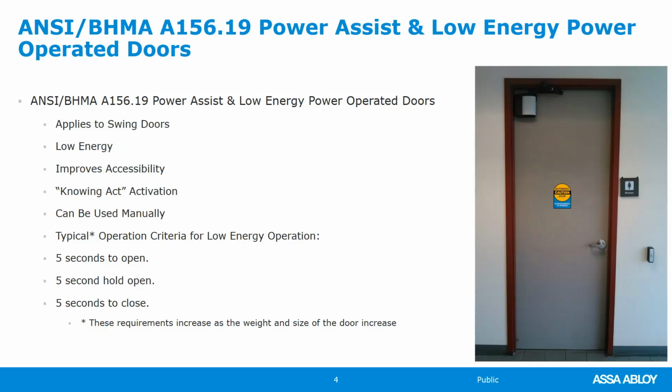Must take at least 5 seconds to fully open. The door must stay open for a minimum of 5 seconds. It must take at least 5 seconds for the door to close. So we refer to that as the 5-5-5 rule. And again, it's typical, but pretty common if a door is set up that way.